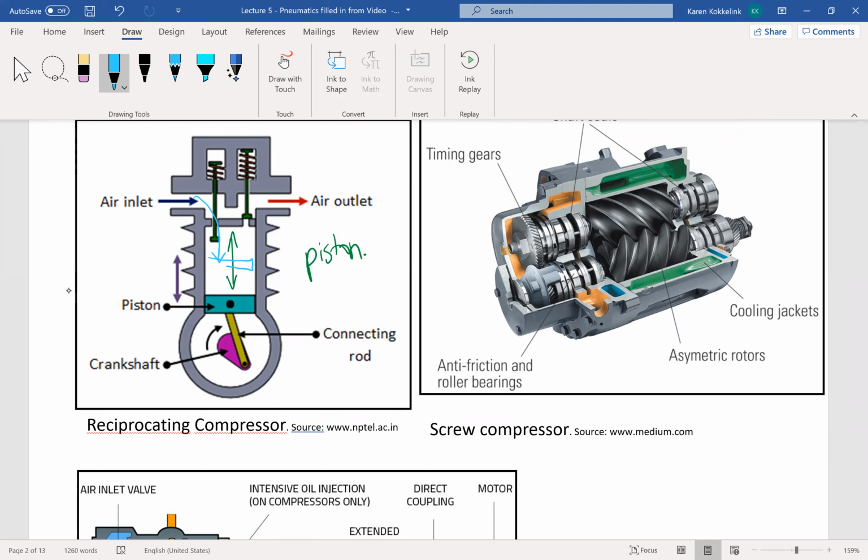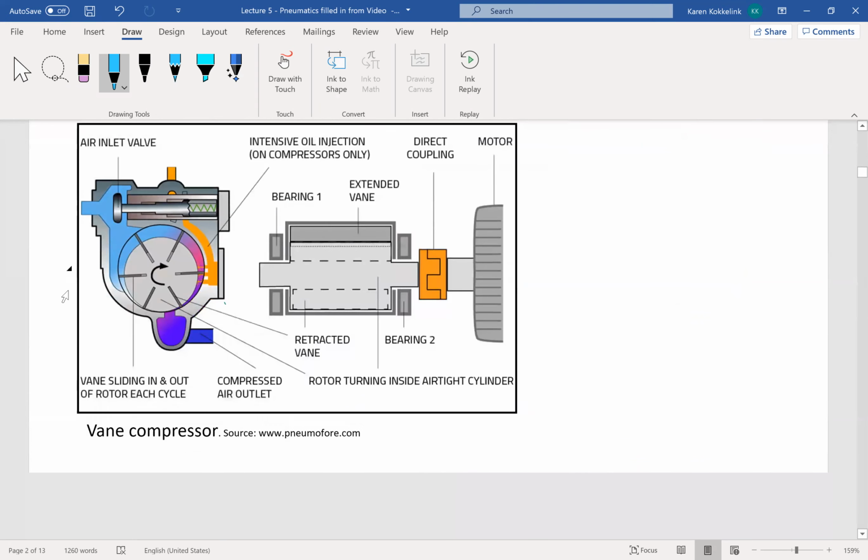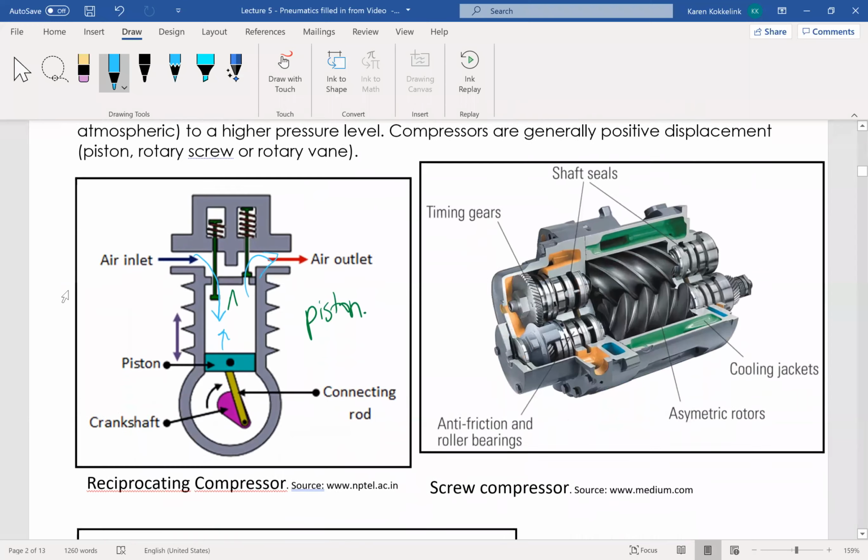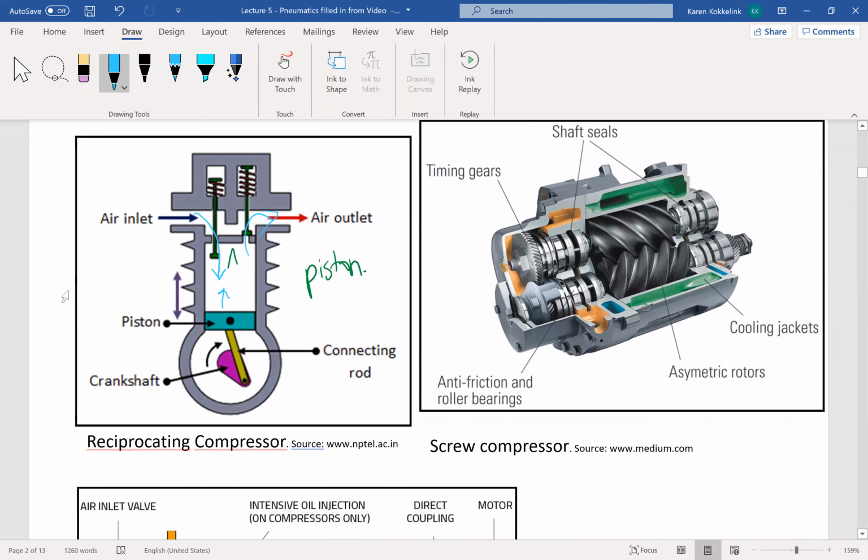It's going to be now sitting up here. The piston moved up here, and now the air is in a smaller volume. So it used to be in this whole volume. Now it's in a smaller volume. So it got compressed, and then the smaller volume goes out. So it must be pressurized. So that's the most common type of compressor. That's what you see on, say, your air conditioning unit. For example, when you pay for the electricity in your air conditioning unit, it's operating a reciprocating compressor.